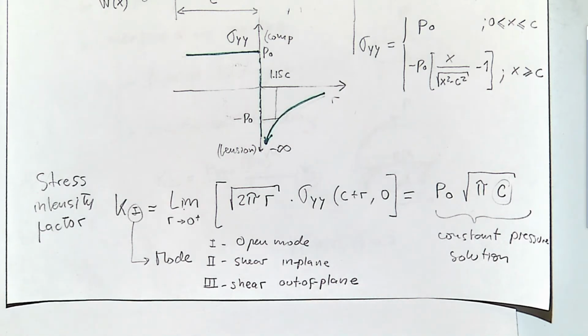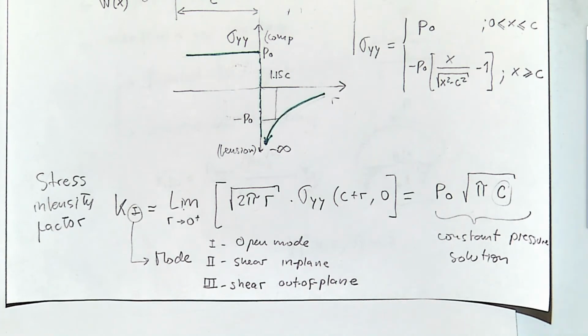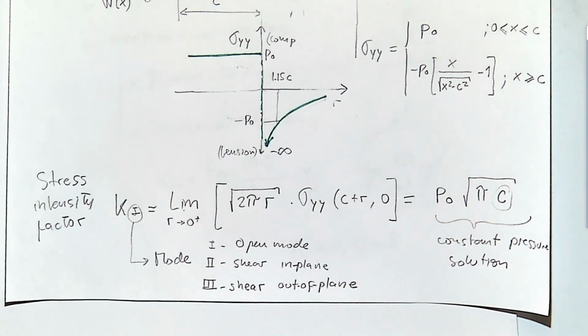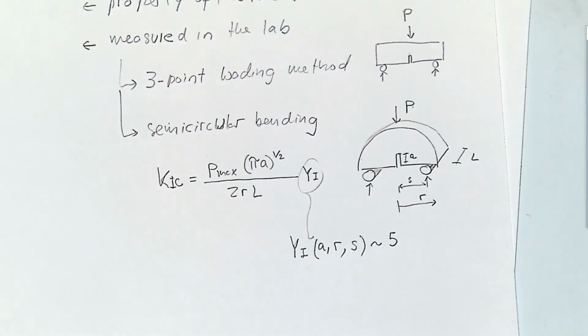Okay. Well, the main concept here is that the longer the fracture, the easier it is to propagate a fracture, because the stress intensity is going to be higher. If you have a longer fracture, it's much easier to propagate a fracture. Yes, Jack? That's only applicable for mode 1, right? No, also for modes 2 and 3.